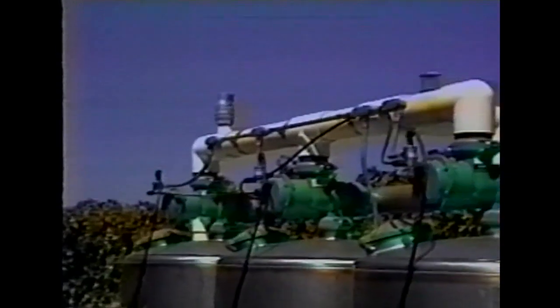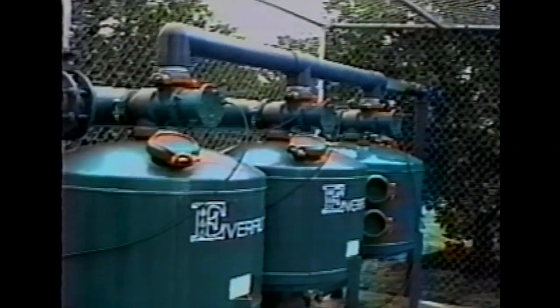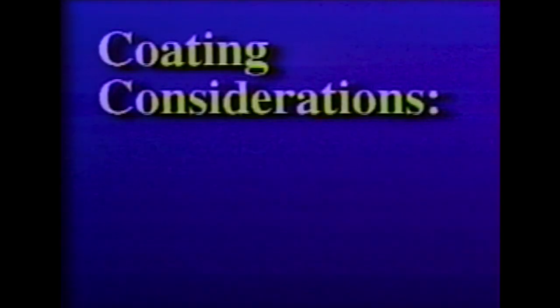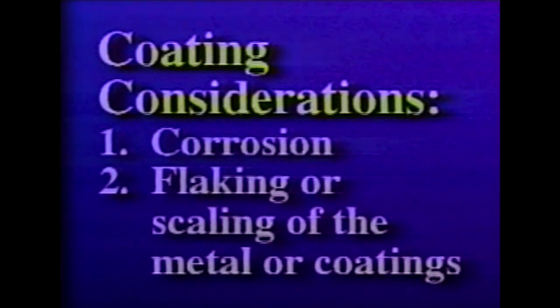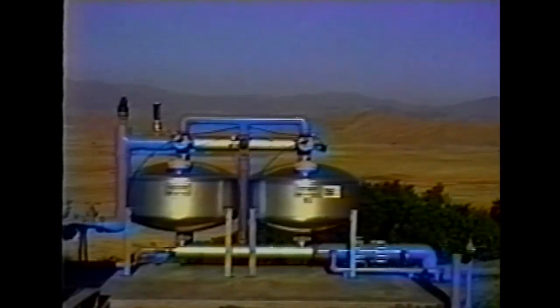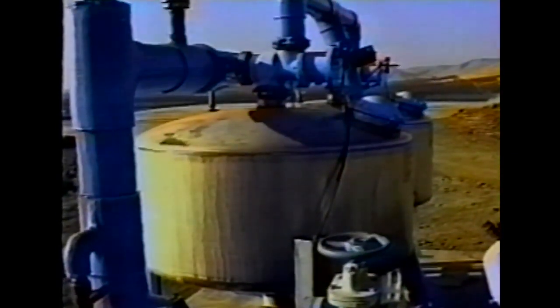There are many types of tank materials and coatings. The most common tank materials are carbon steel or type 304 stainless. Some fiberglass tanks are also made. The primary material and coating considerations are corrosion and flaking or scaling of the metal or coatings. Uncoated carbon steel is subject to corrosion. Type 304 stainless steel is corrosion resistant but not rust-proof. Salt, chlorine, and alkaline water conditions can produce pitting in the metal, which can develop into pinhole leaks.